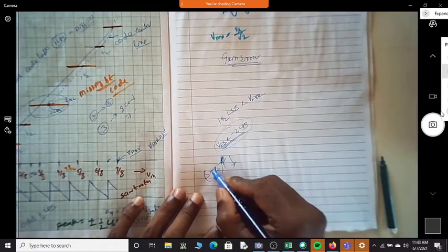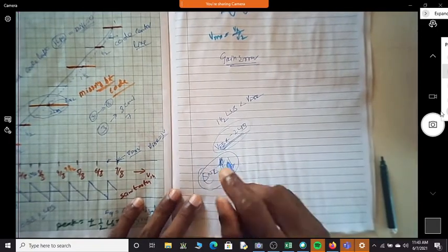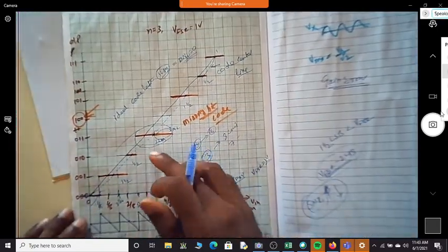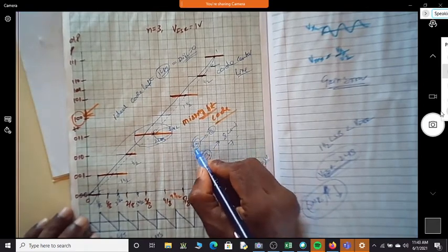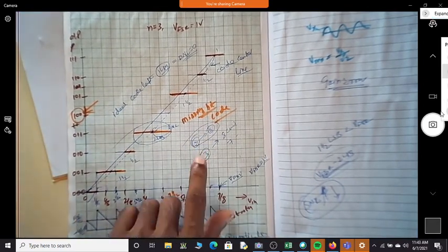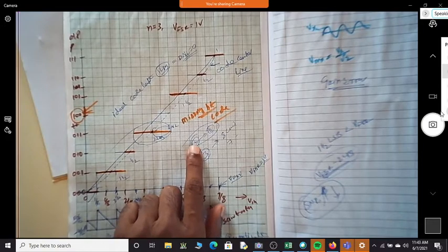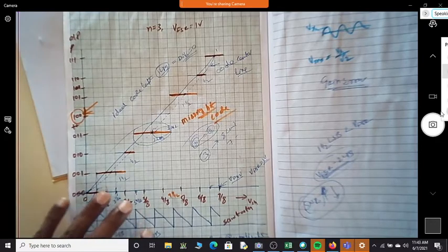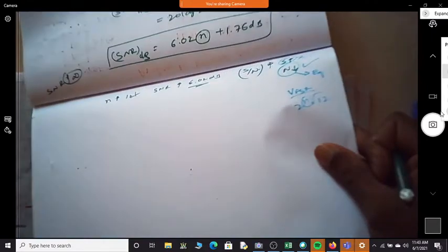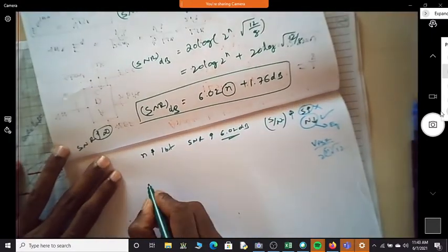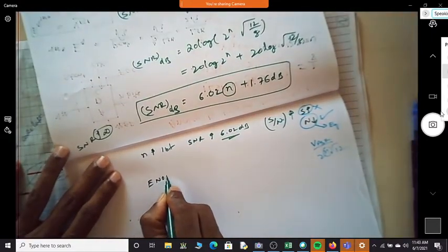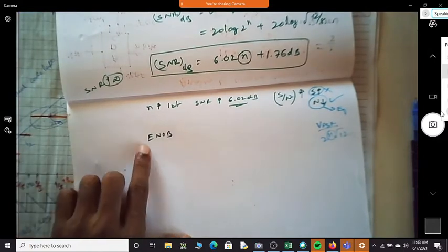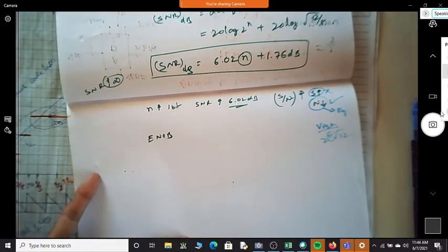When signal to noise ratio reduces, then the number of bits is not 3 now. I will say it is not 3. Why it is not 3 means you are not getting all 8 combinations. In such a case, we will write one more important concept: effective number of bits, ENOB, of an ADC.